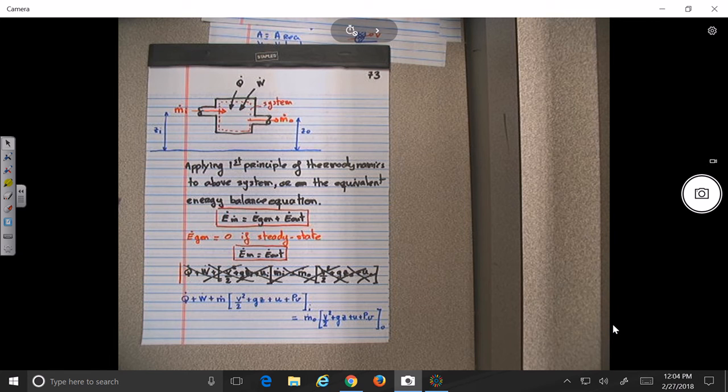Because then you have the compressor, then you have the engine, which is like a control volume, no? But the higher the pressure you have, the more work you can produce, no? So what is the role of the compression? It is to try to transform all the kinetic energy of the flow coming in to what the ideal case would be: to stop it to zero velocity, no? I mean, in order to increase the pressure, you need to take the energy from somewhere. It will be the kinetic energy.